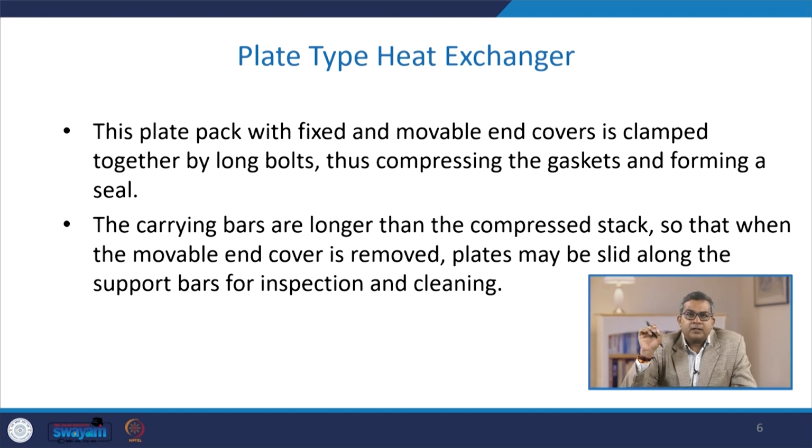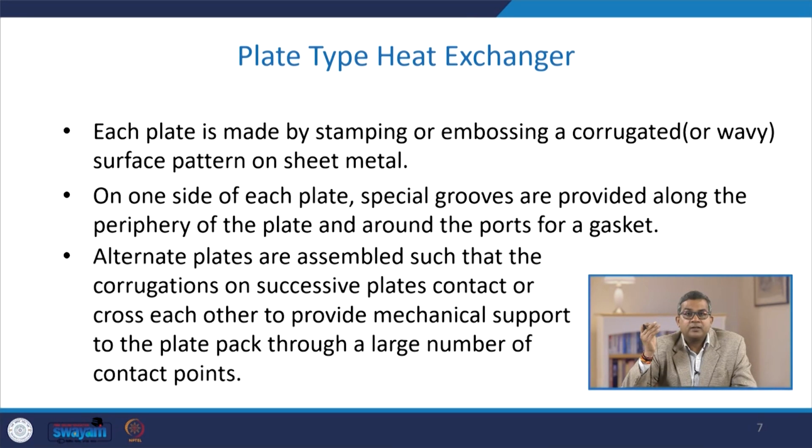Now the carrying bars are longer than the compressed stack, so that when the movable end cover is removed, the plate may be slid along the support bar for inspection and cleaning. See, inspection and cleaning is again very important to have proper heat transfer. Otherwise, the dirt and dust or scales may become part and parcel, and you know that these do not contribute any kind of heat transfer effect.